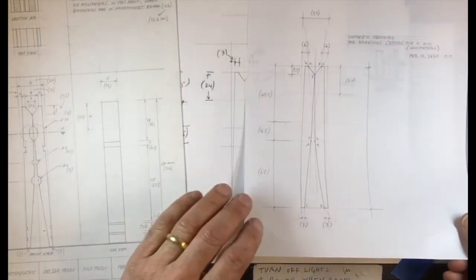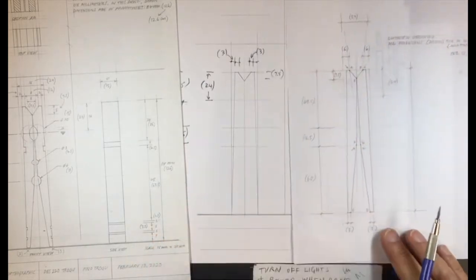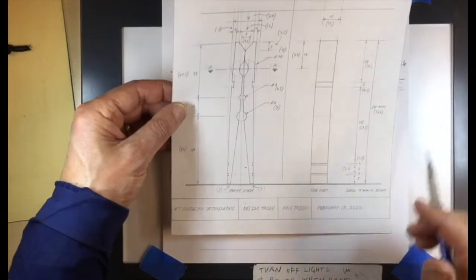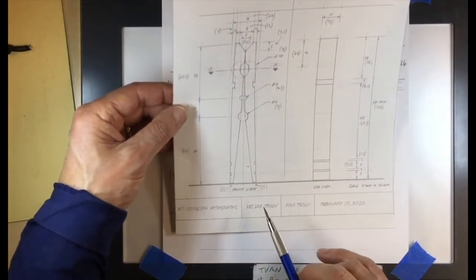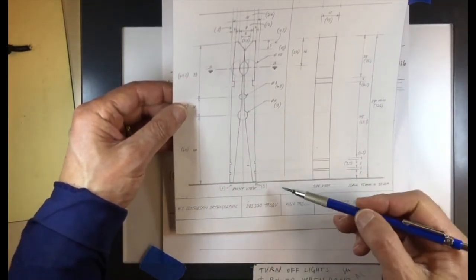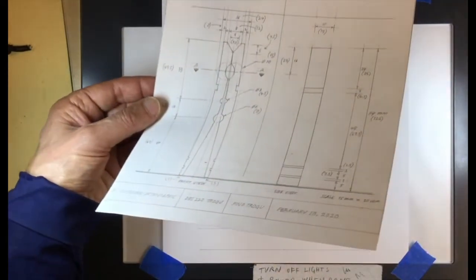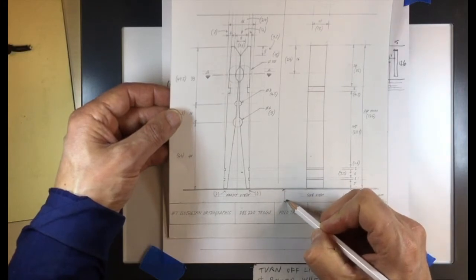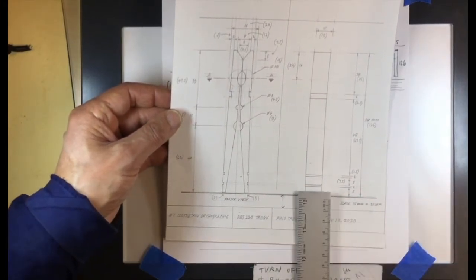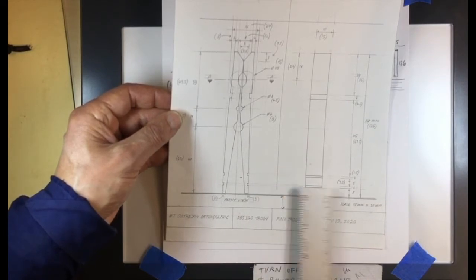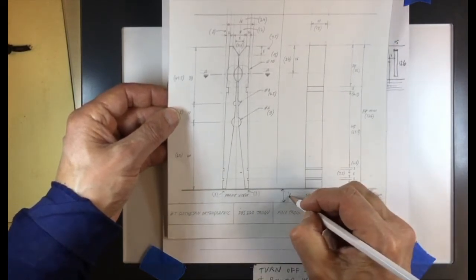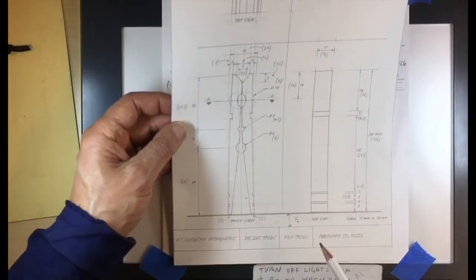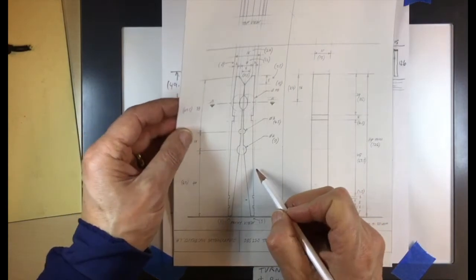Yeah, let's just review some basics so that we are all on the same page. So again, put your baseline at 3/4 inch from the title block. Is that what I did? Or an inch? Wait a minute. Half inch, sorry. Half inch. So the space from the title block is half inch, okay? So that you have more room then to do everything else. We put the boxes at 1 inch from this line.